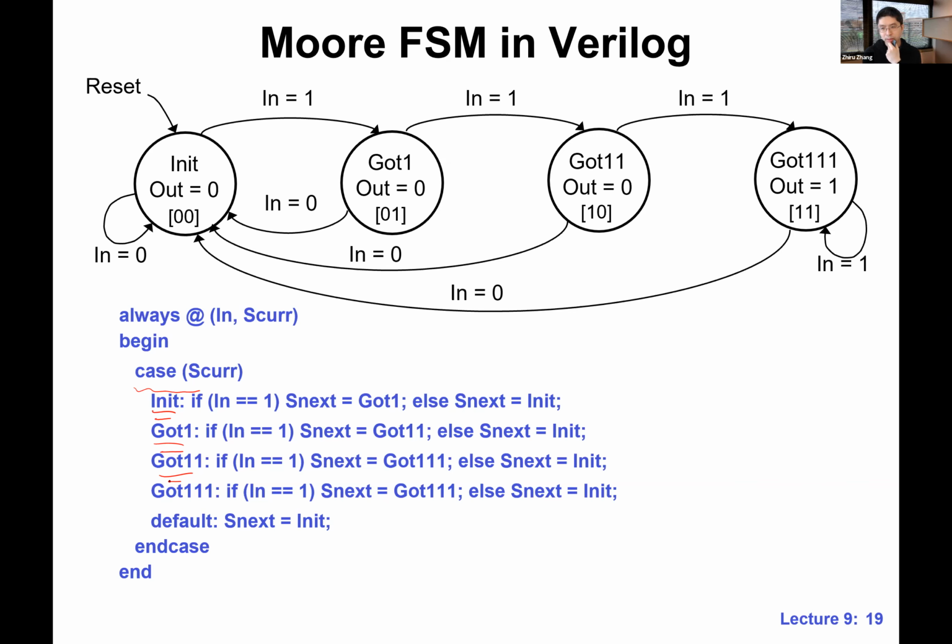First, there's no clock on the sensitivity list. That already smells combinational. But last time, in lecture 8, we did talk about some cases: if a certain output is not assigned under certain input combinations, we may have a so-called inferred latch. If it is indeed assigned under all different input combinations, then we have combinational logic.